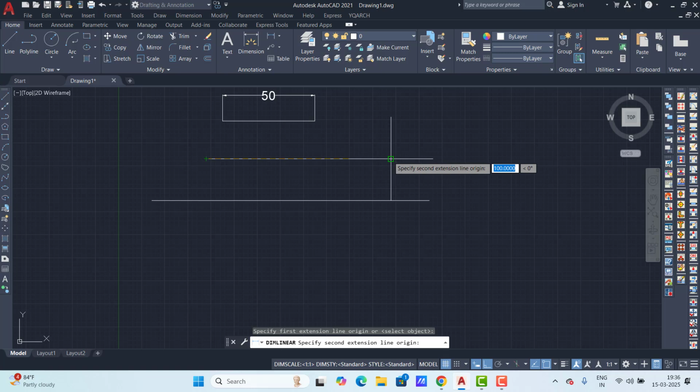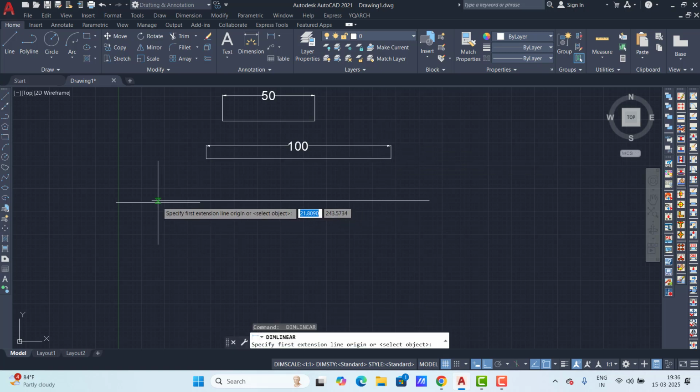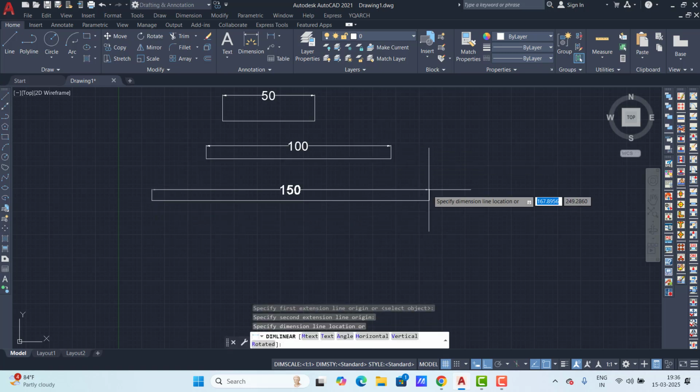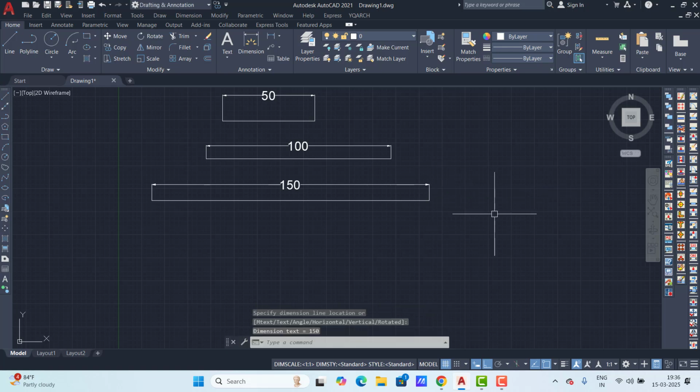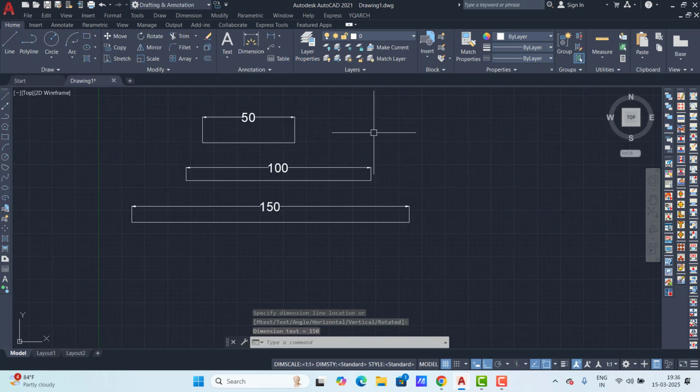Now here we have two lines. Press L, E, Enter. Now I want to increase percentage-wise, so press P. I want to increase the 100 line by 15%. 100 multiplied by 15% gives 15. So we type the percentage value 115 and press Enter.